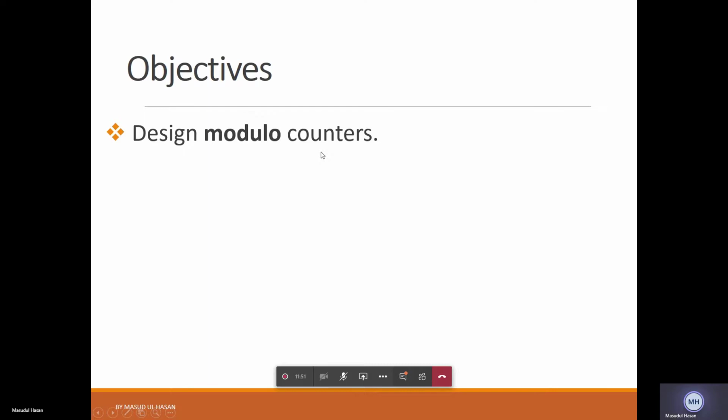Due to this limitation, we will use the available four 7-segment displays on the board, and we will just display minutes and seconds: 2 digits for minutes and 2 digits for seconds. It will display 4 digits and go from 00:00 to 59 minutes 59 seconds.